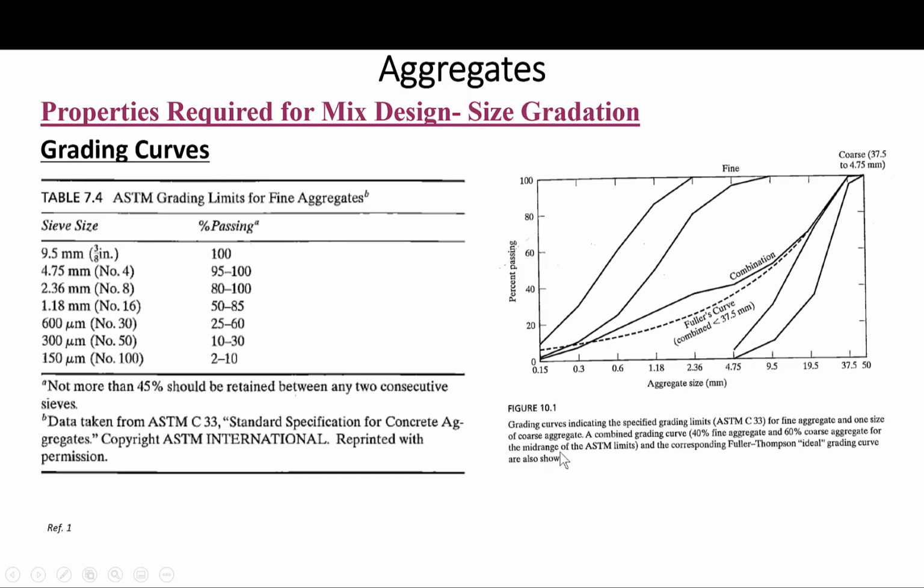ordinate. And again, what we said here, if the aggregates do not conform to ASTM C33, it does not mean they cannot be used to make concrete. It's just that you will anticipate problems, because these limits were established based on experience and what works better. So again, the key is to maintain uniformity to avoid corrections to your mix design, because it is made with a certain grading, and every time the grading changes you have to make adjustments. So uniformity is key.